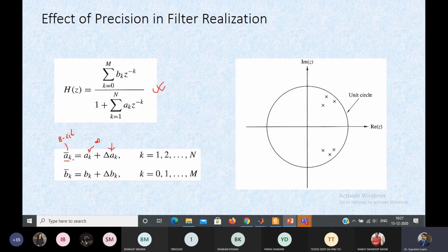Okay, and similar is true for the poles and these zeros, right? Now what happens is, say as I said, our value is 5.12, and because of our fixed point representation, these two get cancelled, and there was another pole at 5.13 or say 4, but because of this process, this 4 is also getting cancelled, and you can see that two values appear to be the same because of this imprecision. So the two poles will fall in the same location, so definitely it is going to change the frequency response.